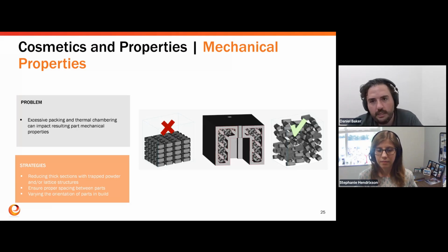But the DFAM process is pretty simple because most designers are designing for molding because that's how they know. And it's just a few small tweaks or changes to optimize. And then once you get into what I talked about today, like nesting, for example, it's a pretty easy visual to show you. Like you've got a 15-inch by 12-inch by 15-inch box. The more you fit into that box, the cheaper your part is going to be. And then they start to see that, and they'll either work on assemblies or splitting their part into multiple pieces, or consolidating assemblies to fit in that box to really drive that cost out.